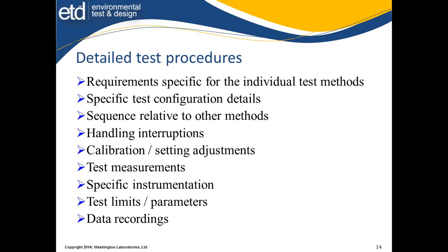How about humidity mixtures? It happens in a lot of cases, but we need to develop this step-by-step, how long, what am I going to do for that test? Am I going to expose various sides to sand and dust exposure, or does it stay with one face only? If I've got an item that's installed in a vehicle for the sand environment and only the front face is exposed, why would I expose the rest of the unit to the sand when it's never going to get there in the real world? So we need to look at how the installation contributes to this.